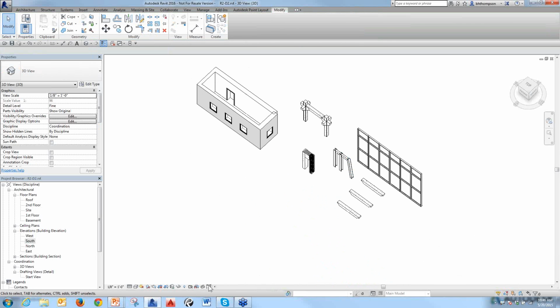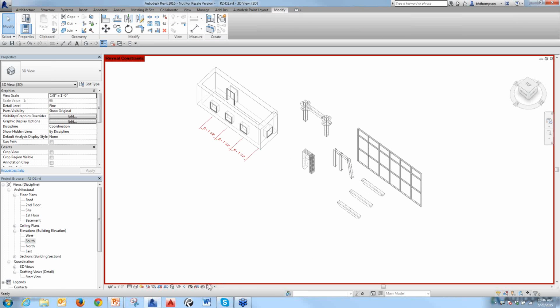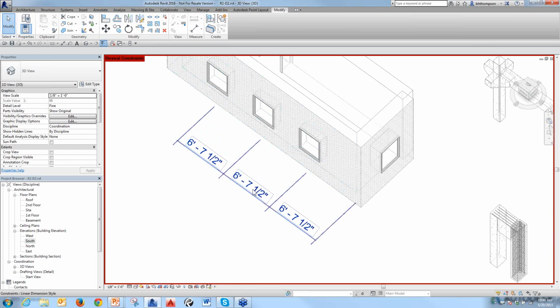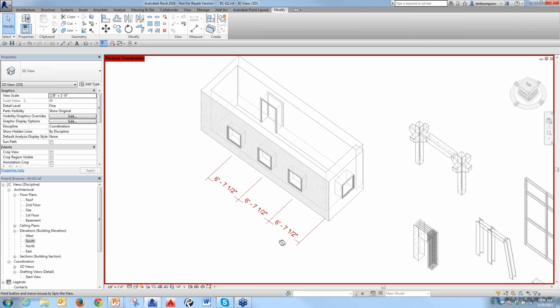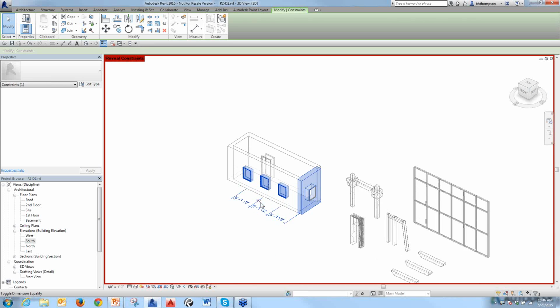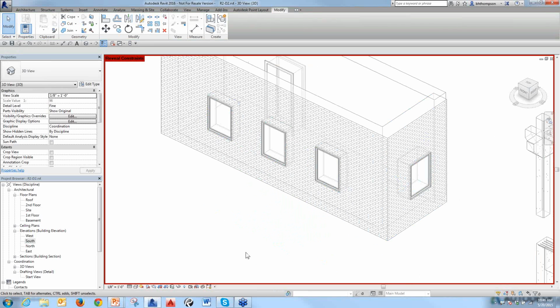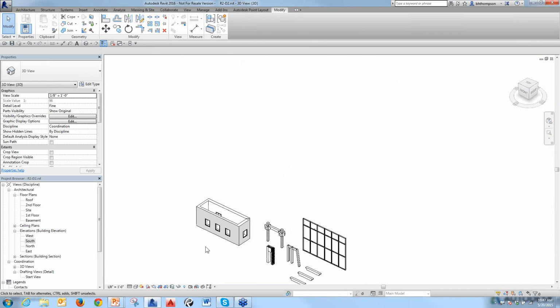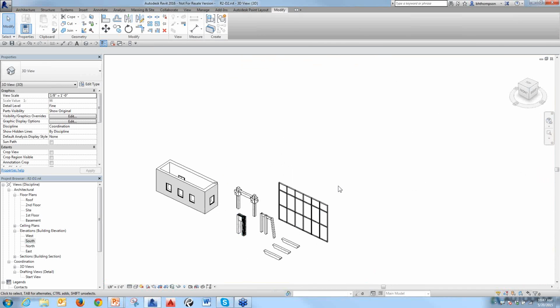The other one I like, from R2, is this little button right here, Reveal Constraints. I use this one all the time when I go check people's stuff out. I can turn that on, and I can see what's been equally constrained within the model, displayed in 3D. I'll just go out to a whole model, click on this, and see who's locked what in the drawing or what's equally constrained. It makes it really easy. I can select it and unequal it, and now it's gone and it disappears. I'll hit undo and bring that back. But that's just been a huge tool, this Reveal Constraints. I use that all the time when I'm trying to assess models.